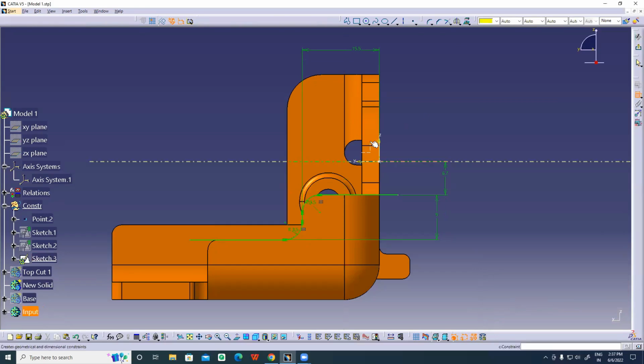And to make this a fully constrained, fully defined sketch, I have to create this dimension from the vertical axis to the end of the line. This value applying as it is, and also I'll be applying this value. After that, what I'll be doing is creating a line, something like this, and make sure the lines which you're creating are above the part, bigger than the part.